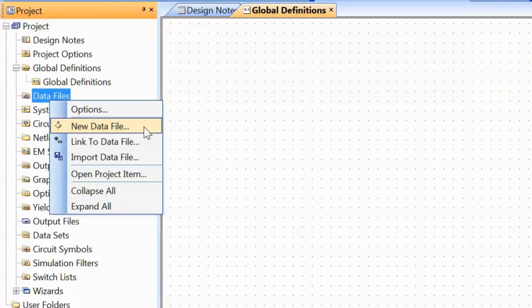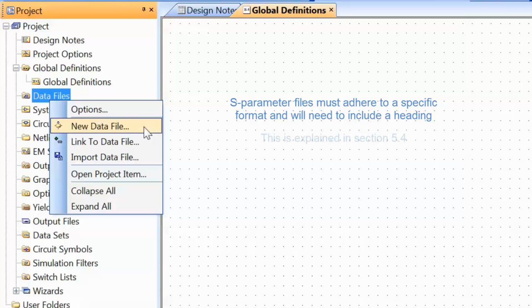And this can be very useful, and we will see this specifically in one of our tutorials. When, for example, you're getting your S parameters from a book, you see an exercise and you want to check it out with a simulator. You've got the S parameters there on a hard copy, and you want to put them into the simulator. You can just create a little file yourself with the S parameters. The other thing that you can do, if you have a data sheet with a list of S parameters, you can just cut and paste those S parameters from the PDF file into the text file here, save it with the right extension, and you've made the S parameters from the data sheet directly usable in the simulator.